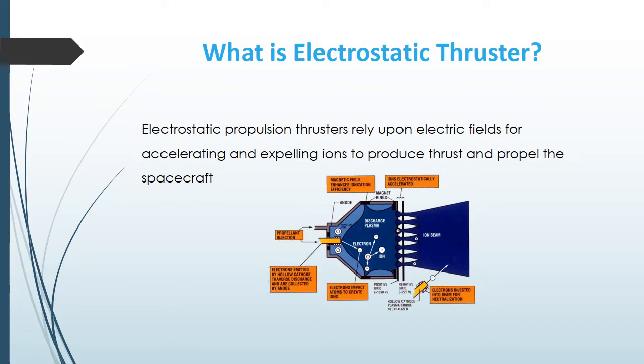The ion acceleration is achieved through several differing means, including the conventional electron bombardment method or the electron cyclotron resonance method, which electrically charge atoms from the onboard fuel supply. This fuel supply is an inert gas, often xenon or krypton, which is injected into the ionization chamber, then expelled for propulsion.